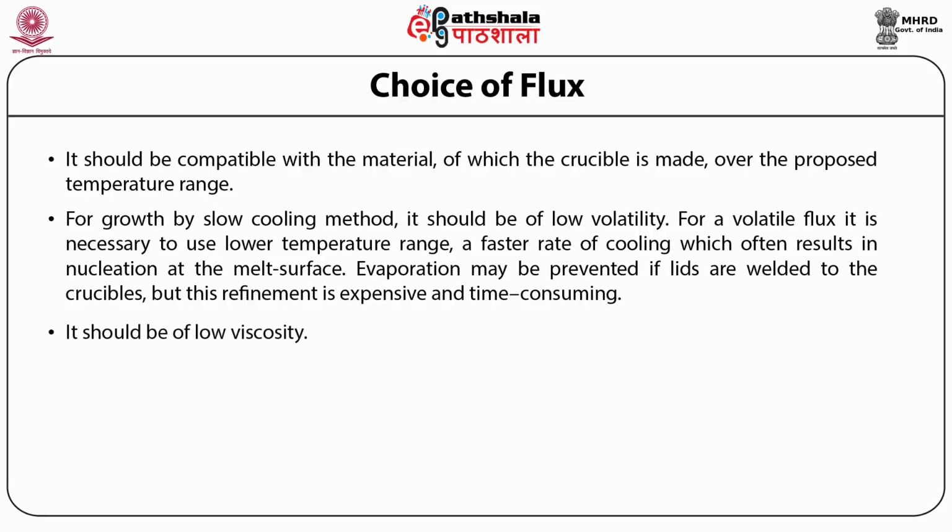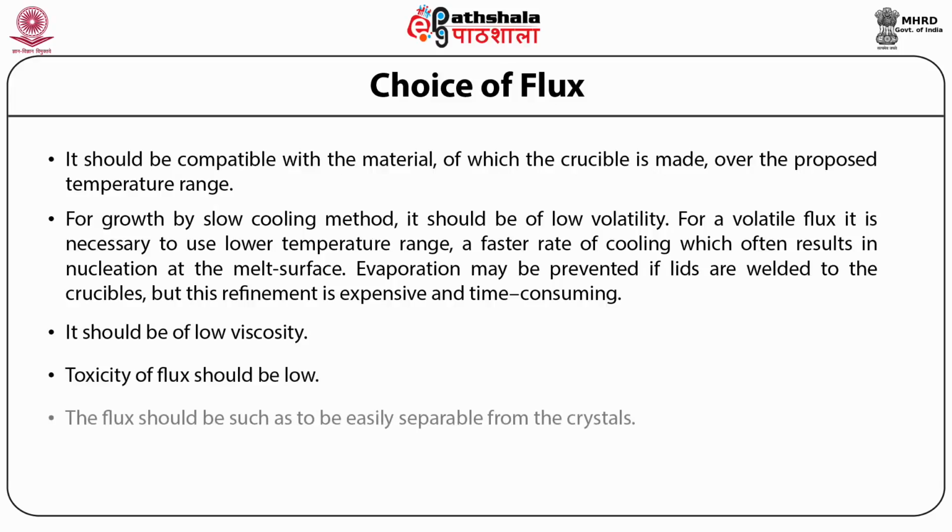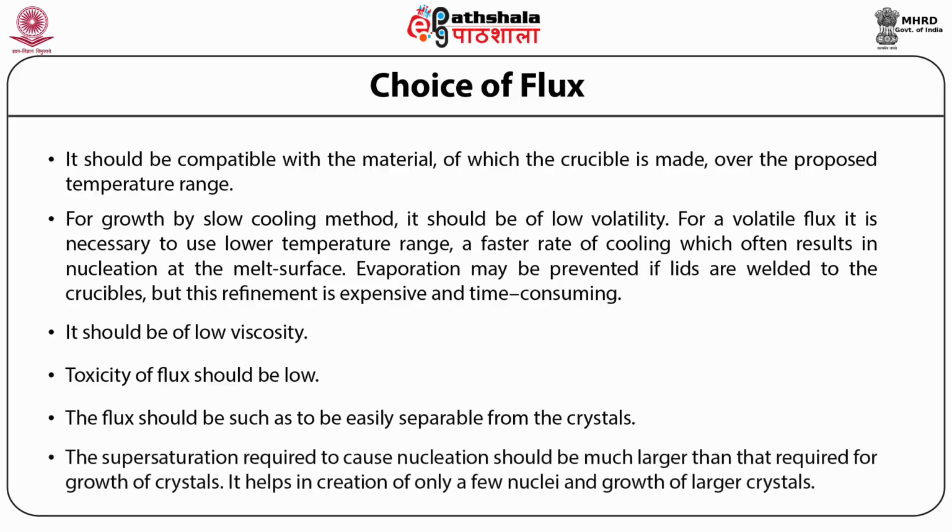It should be of low viscosity. Toxicity of flux should be low. The flux should be such as to be easily separable from the crystals. The supersaturation required to cause nucleation should be much larger than that required for growth of crystals. It helps in creation of only a few nuclei and growth of larger crystals.